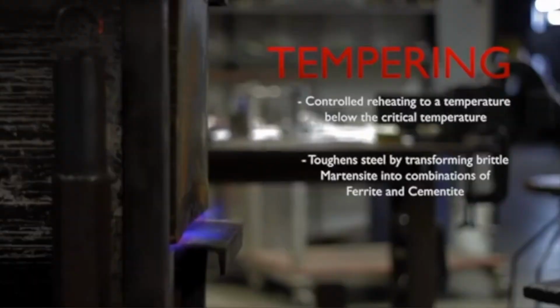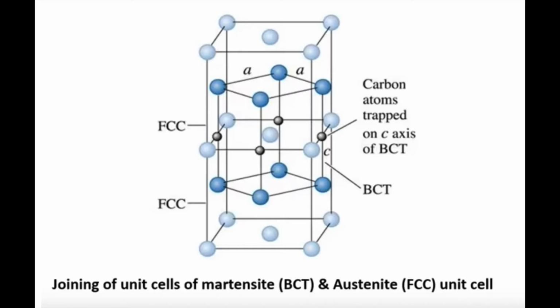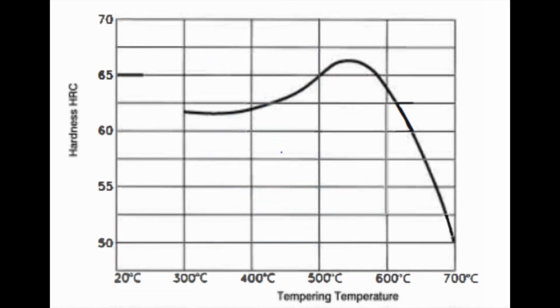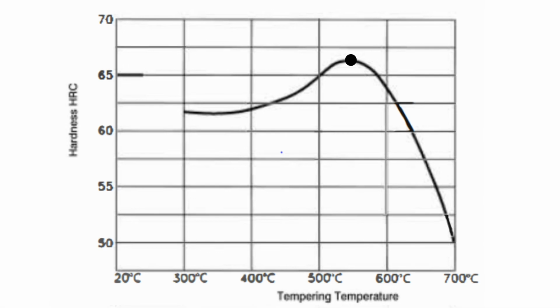Tempering is a process that heats a metal until trapped metastable atoms causing internal stress can diffuse out of the BCC ferrite lattice. This reduces the internal stress. Shown on screen is a tempering diagram for 2 hours for AISI M42. In the diagram, the peak hardness is 66.5 HRC at a tempering temperature of 540 for 2 hours. This reinforces the selected heat treatment schedule.